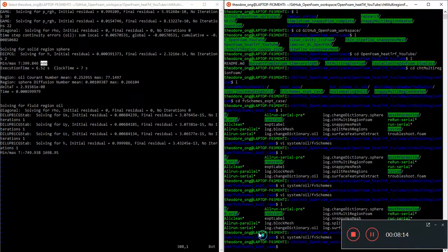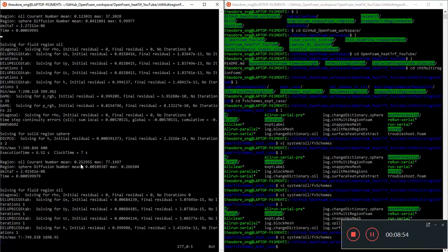That's why I changed it to 400 Kelvin, and nevertheless it's still giving me the same funny result, where the temperature fields are oscillating, diverging in this sense. Oscillating meaning the minimum temperature is below 0, or below 300 something, which is below our start temperature. In the oil region, it's kind of weird, all this minimum and maximum temperature.